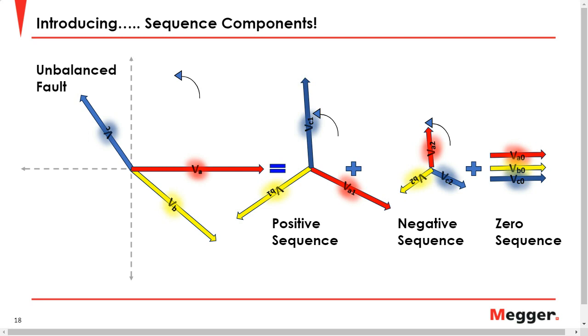Negative sequence, very similar. Now, also keep in mind, look at the magnitude here, and this is just relative to the other sequence components. With the negative sequence, we have the same thing. We have a lower magnitude, which means that we do still have overall that counterclockwise rotation occurring. This is fighting against the positive sequence rotation that we have.